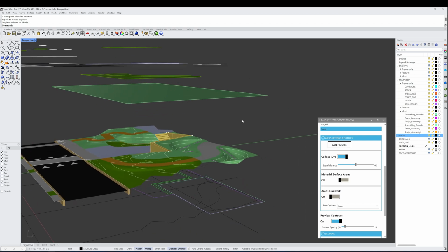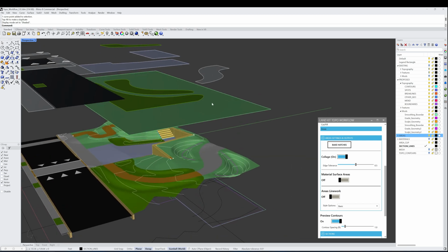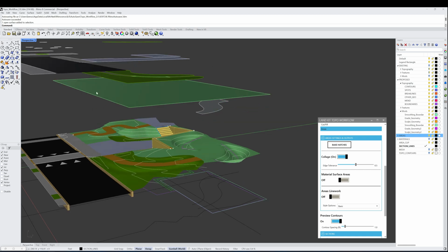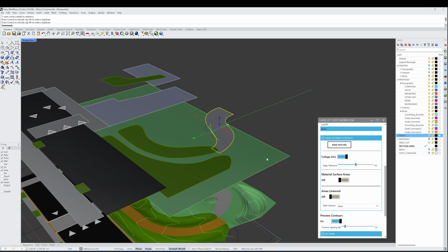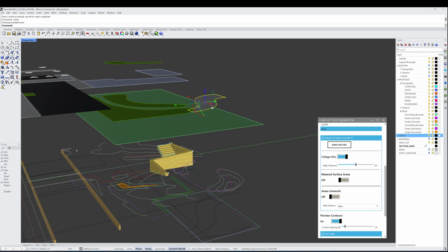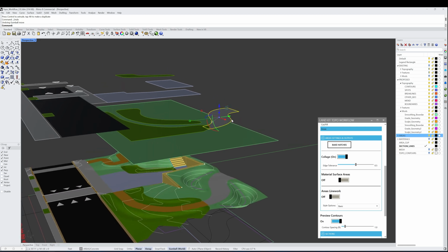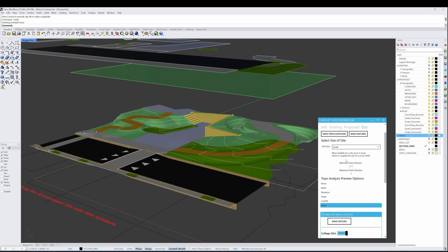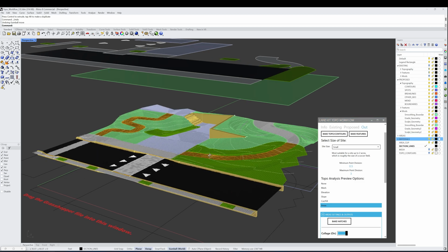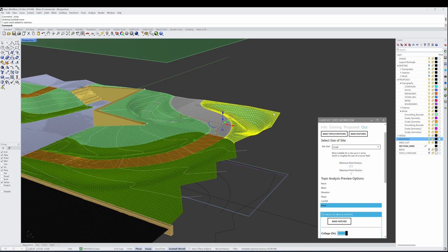But how the collage actually works is by giving precedence to some surfaces over others based on their elevation in space. So for instance, if I wanted this concrete little plaza path here to be just lawn, I could delete this surface, but I could also just take this surface and lower it in the Z-plane below this larger lawn space, and you can see it disappears because everything that's above will take precedence over anything that's below. So it allows us to do this fun collaging action where we can just shift around these surfaces or change the surface shapes or cut them and then have them cut out from each other automatically. So these will all mash down together when we bake these out. So if we go up here and hit the bake button, these are going to bake into our materials layers, and they're also going to be separated by their different material layers as well.